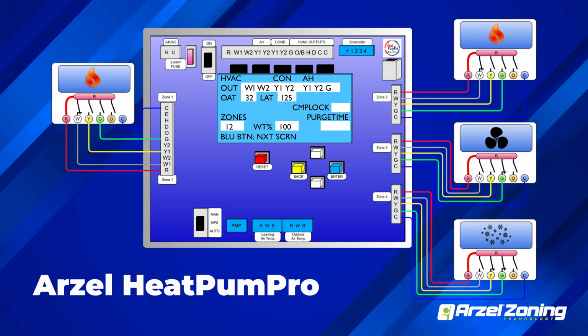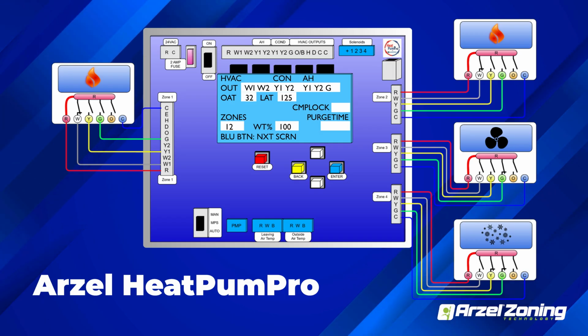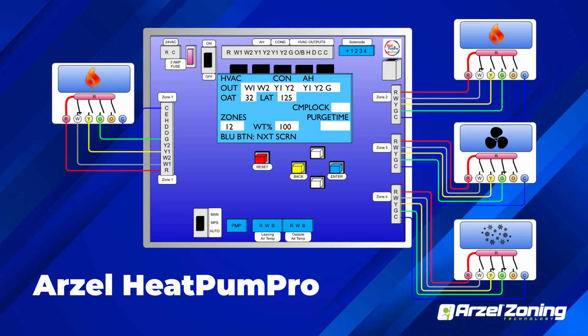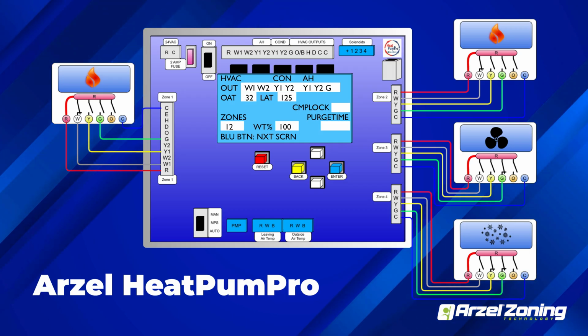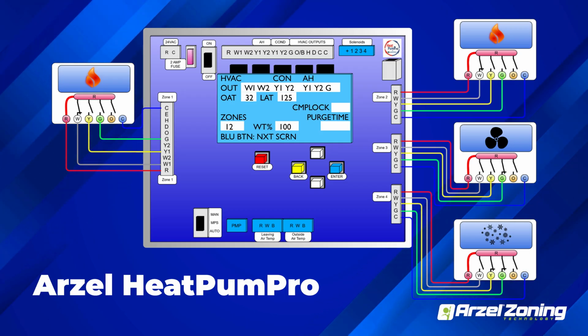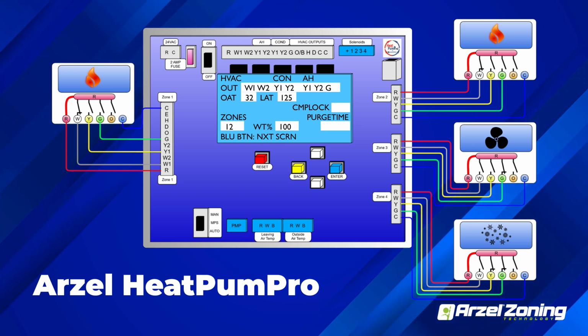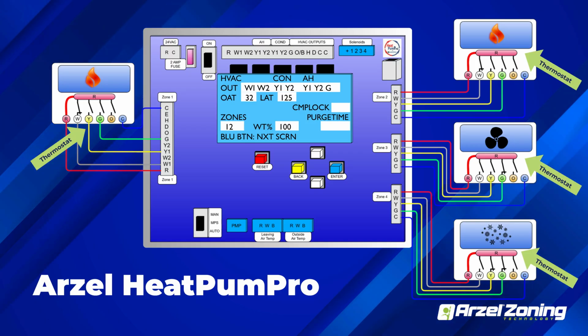And one of the things with the Arzel HeatPumPro is that your weight percentage does not have to total out to 100%. It can be less than 100. It can be greater than 100. But with the zoning panel, we can have thermostats calling for opposing things. The zoning panel provides the rules that prevent opposing or conflicting calls from going to our equipment, and that allows everything to work together nicely. But we have our thermostats.